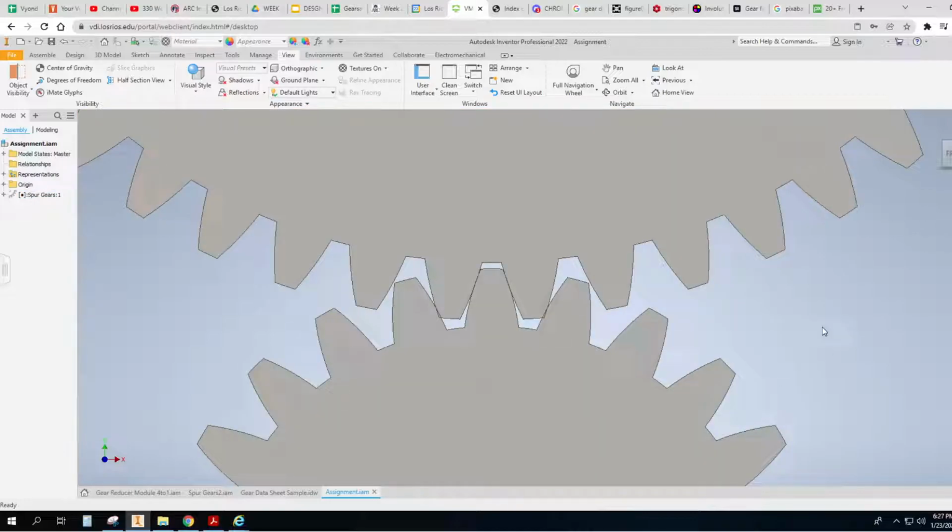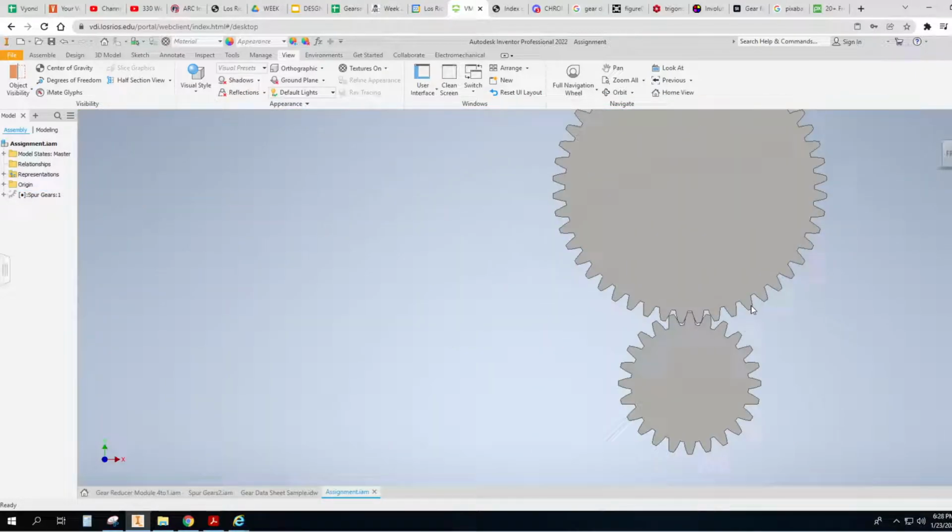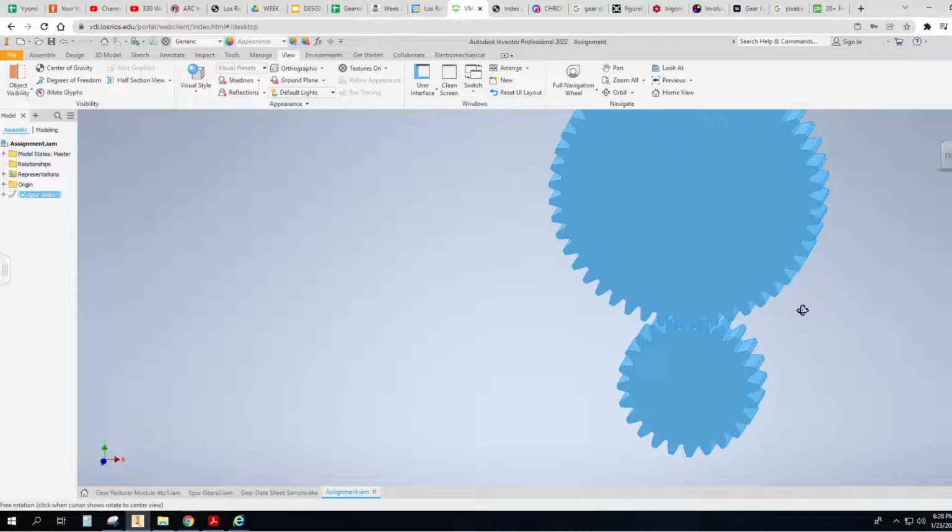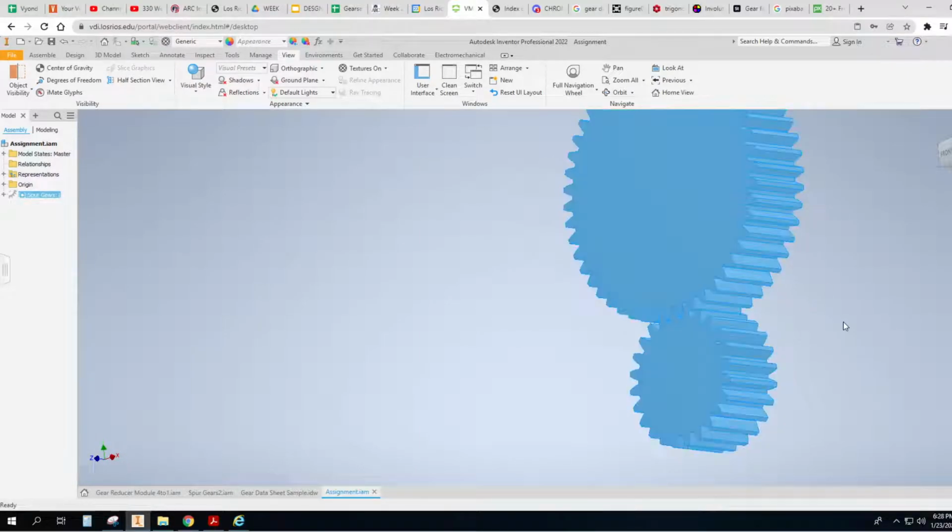This is just kind of a cool thing. That's the root. Above this line is the addendum. So that's the pitch diameter or the pitch circle. You've got the outside diameter. You have the root diameter. And you do have a center. Okay. There's also something called face width. Now in this one, I made them both the same. That's not a requirement, but it's a standard way of doing it.